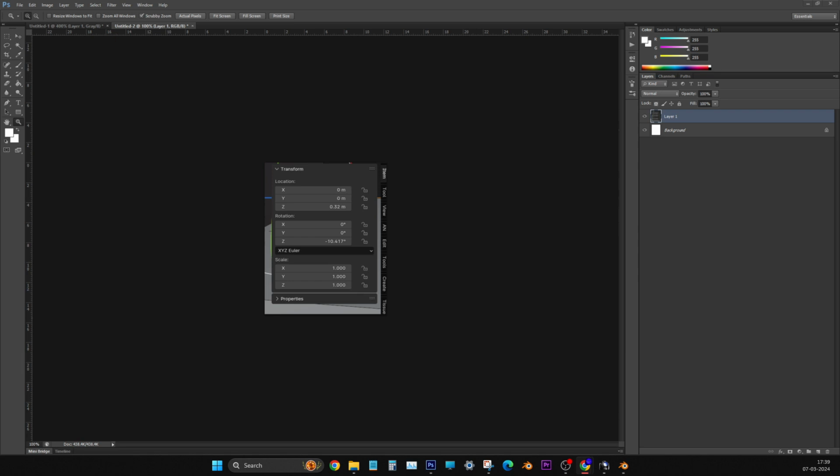Press dot to zoom. Now take your cursor to the left side panel, the UV panel, and select any one face. Now press three on the keyboard, that is the face select mode. Now press select. So the backside is getting selected. Do you see that? On the right side, the backside is getting selected. Okay, now select the next face.